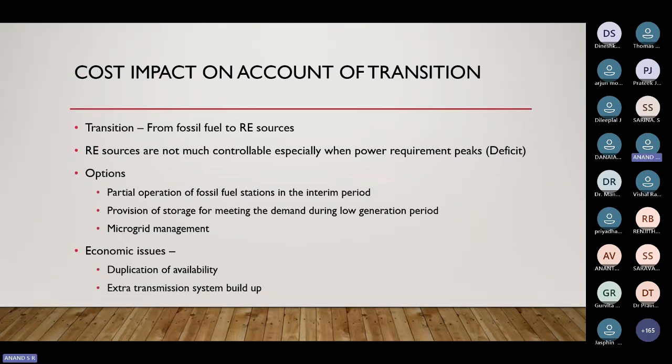One reservoir may be available with the existing plants, and another reservoir has to be provided, but that land has to be acquired, and the topology has to be suitable. The head between the 2 reservoirs and the distance between them have to be within ranges. So there are some constraints in locating pumped storage schemes.